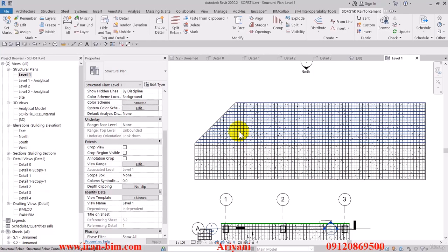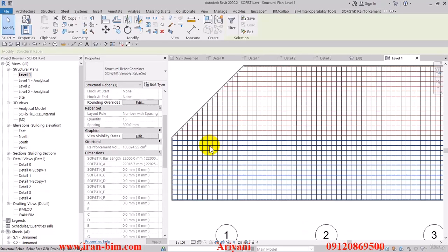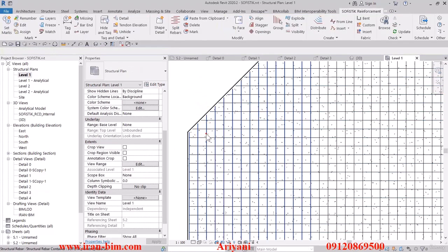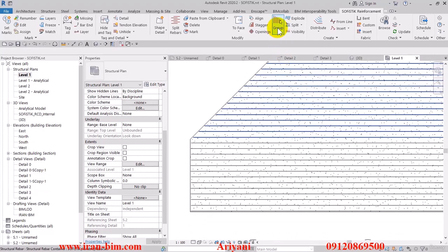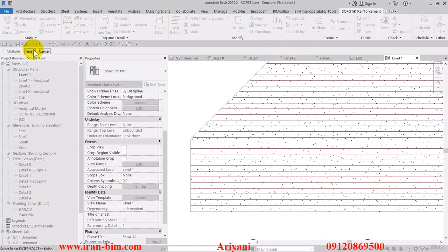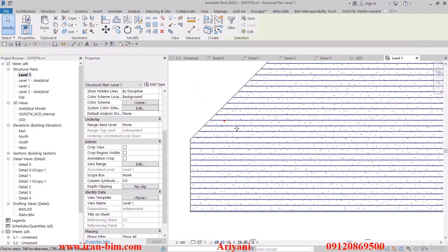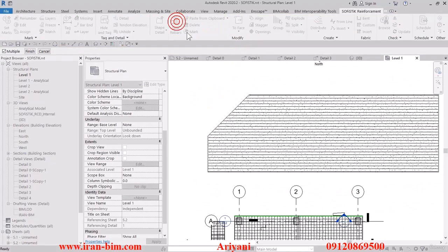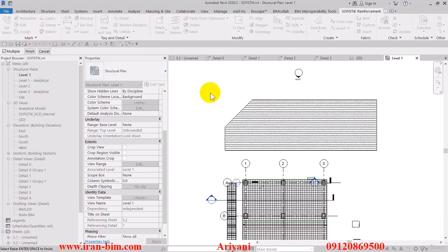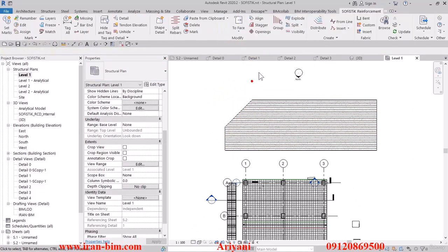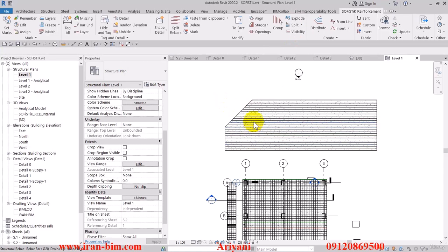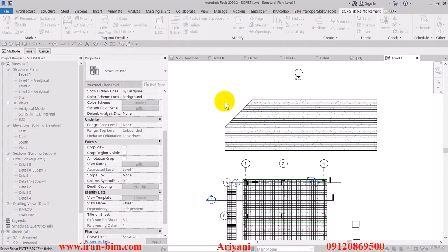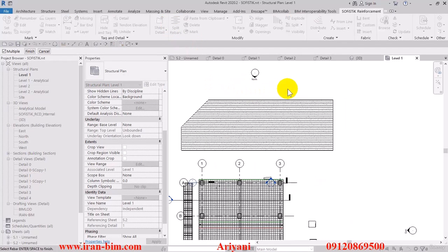Alright, Ctrl Z. Let me just go here and delete this so that we don't make any mistakes. Alright, after that select the group tool and select these two parts to group them up and finish it. Alright, they've been grouped. So now I'll select the split tool and click on the surface. Oh, because we've grouped them, we can't actually split them. So I'll ungroup them. Alright, so I'll select the split tool and then I'll select all of the network here. So finish it up now.